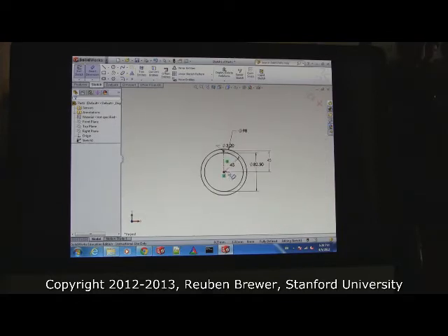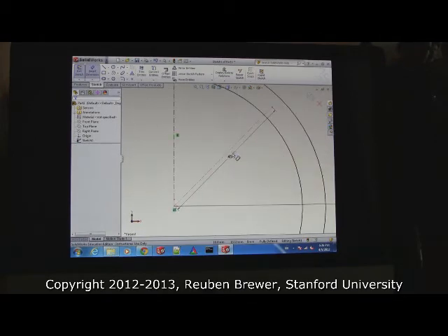Watch this. Watch my screen. If I'm way out here, see, I'm trying to click the blue line, but I can't. It keeps trying to select the other one. Anytime you're about to click something, it shows in red. So right now the 45 is black. Now I'm trying to click and it's red. That means I'm about to click it. What's the solution for this? Zoom in. Now I can click either one of them easily. So if you're having issues where it seems like it's not clicking the right thing, it's because it's not.